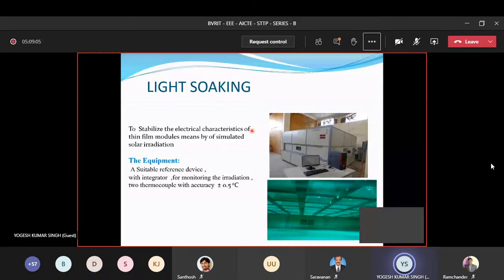But whenever you install a solar system in any location, you must find out that no shadow will come across that location, because if shadow falls there, your module will not work properly. So whenever you install your solar power plant, always make sure the area is shadow free.